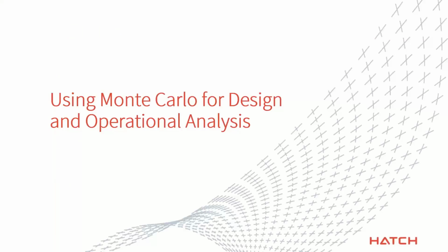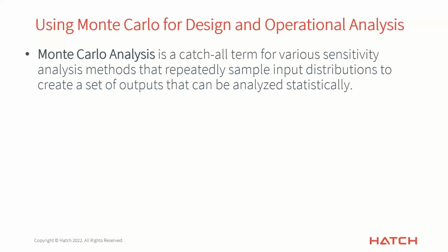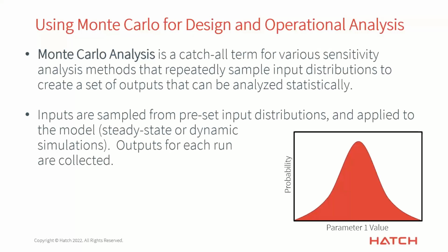Okay, so on to using Monte Carlo for design and operational analysis. If you've not heard of it before, Monte Carlo analysis is not one specific technique. It's actually a catch-all term for various types of sensitivity analysis methods. But they all share the same idea. You run a large number of simulations, and on each one of those runs, you sample a bunch of different input distributions to create a set of inputs that you put into your model. Then you run the simulation, and then you can analyze all of the outputs that you get.